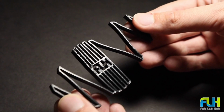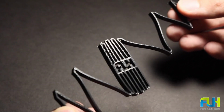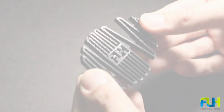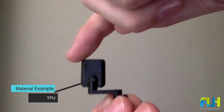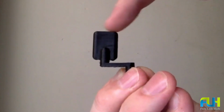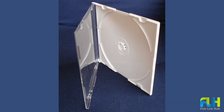Flexibility governs how easily a material can be deformed without damage to the structure. One of the most flexible materials is TPU, which has properties similar to rubber. Other materials such as ABS, PETG, and nylon are somewhat flexible. Among the most rigid materials are PLA and HIPS.